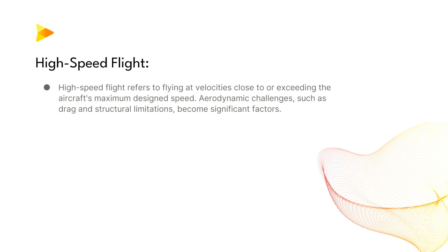High-speed flight refers to flying at velocities close to or exceeding the aircraft's maximum design speed. Aerodynamic challenges such as drag and structural limitations become significant factors. So angle of attack must change as airspeed varies through the thrust to maintain level flight. At a very high speed in level flight, it is even possible to have a slightly negative angle of attack.